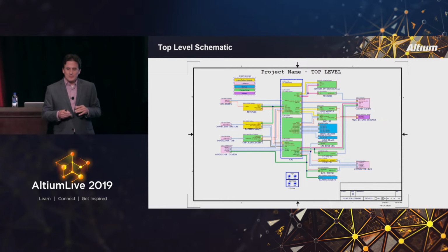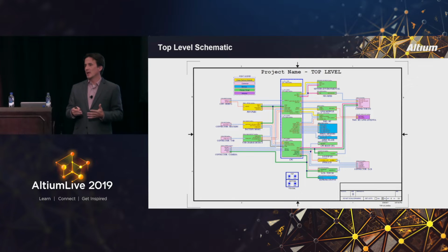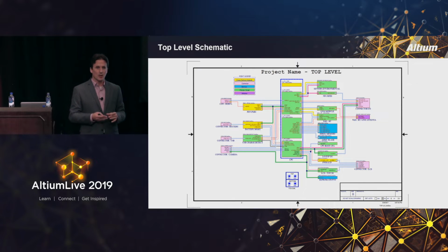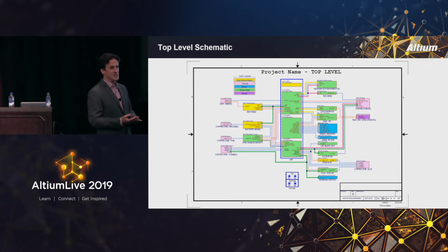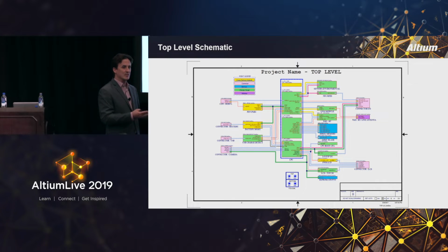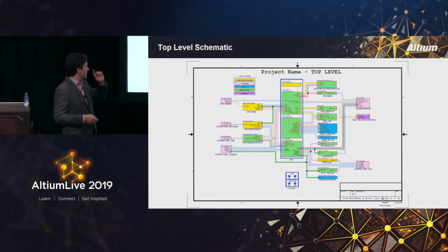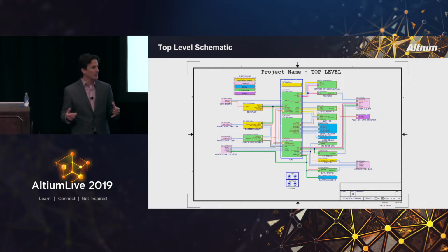But what it allows me to do is, my connectors are one of my absolute focal points in my design. Are they protected via ESD? Are they positioned correctly? Have I done all the things I need to deal with EMI on those connectors? Same thing with power delivery. Those are essential elements in my design. I don't think I need to go into further explanation on that.